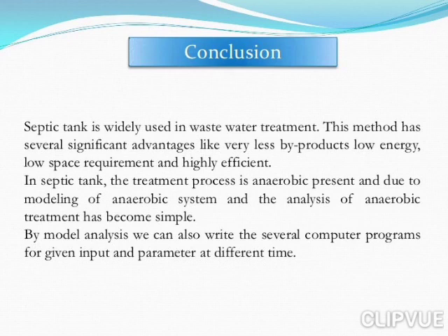So, septic tank is widely used in wastewater treatment. This method has several significant advantages like very few byproducts, low energy, low space requirement, and high efficiency. In a septic tank, the treatment process is anaerobic, and due to modeling of the anaerobic system, the analysis of anaerobic treatment has become simple. By model analysis, we can also write several computer programs for given input and parameters at different times.